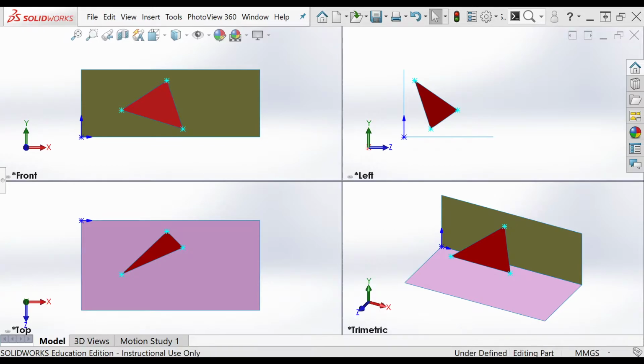So that means in the front view, the elevation, it is 45 millimeters from our origin on the left. The next value is its altitude, how high it is off the ground, and it's 30 millimeters, and you can see that in the picture on the right, top right. And then in the bottom left image, you can see the z value, which is 60.